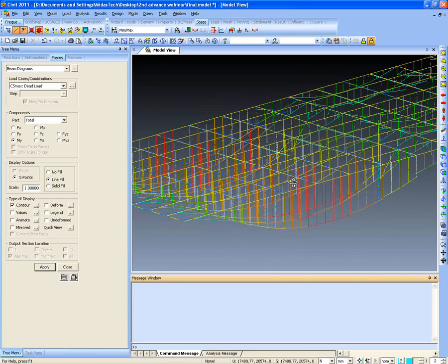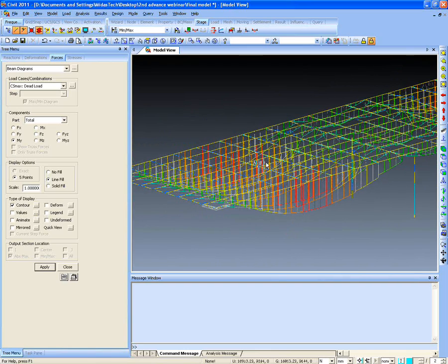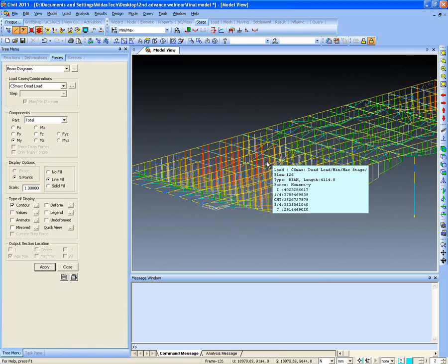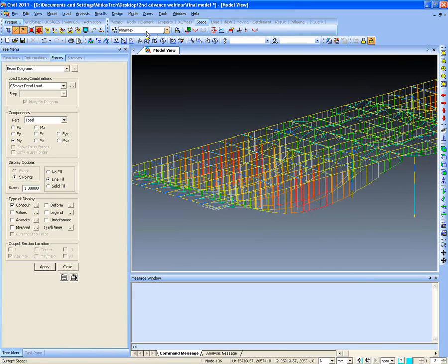It might happen that the bending moment on a particular element is maximum in CS5, but there are 20 stages, so this option will show you the maximum moment at any point of time in a segment.